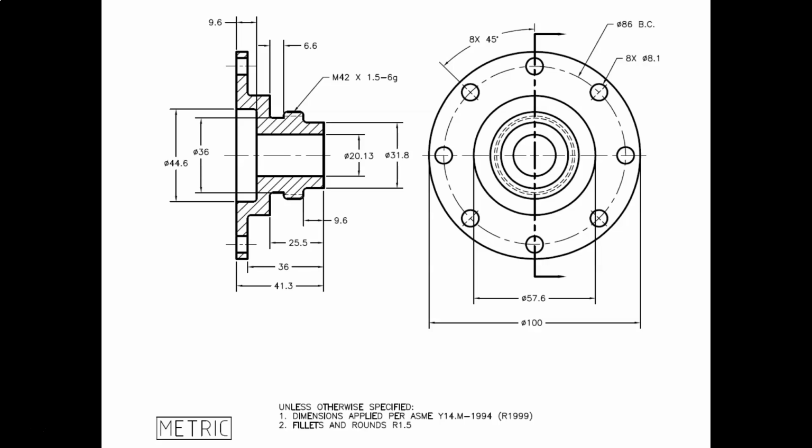Once you get the drawing shape defined using the orthographic views and section views and auxiliary views and all that stuff, then you're going to turn your attention to the dimensioning part of it. Okay, and you're going to approach it just like I was talking about, with understanding what the basic parts are. And that's really where our process for dimensioning starts.